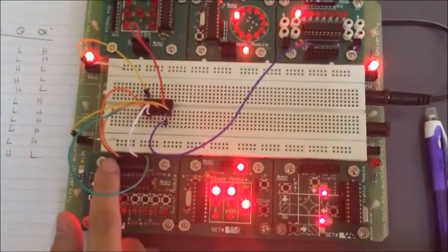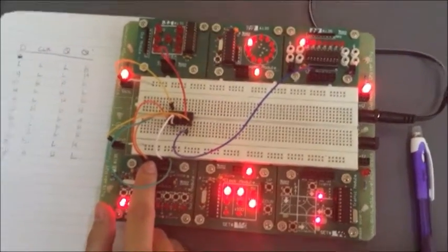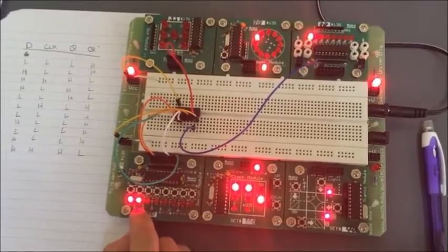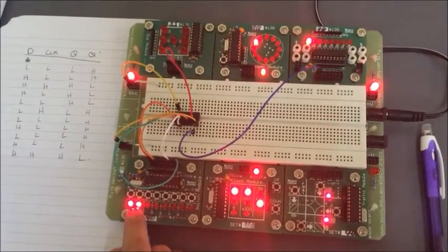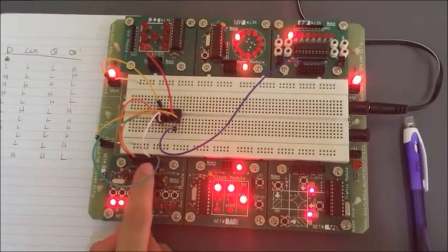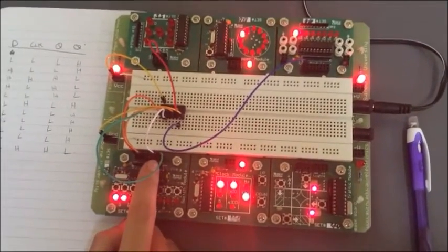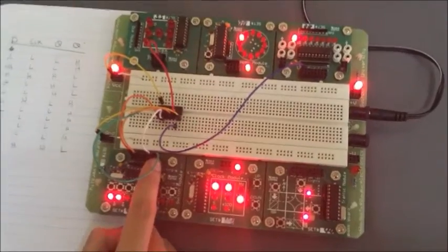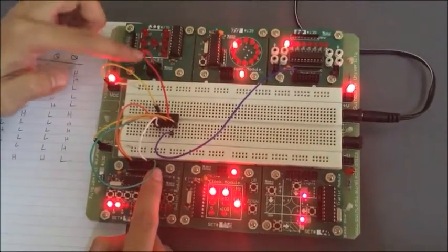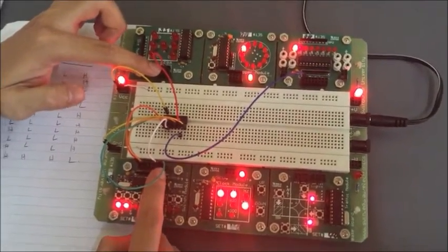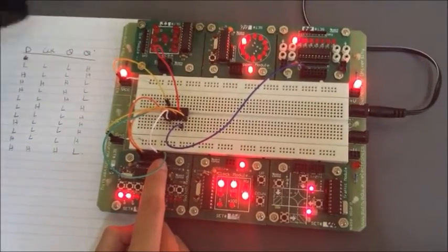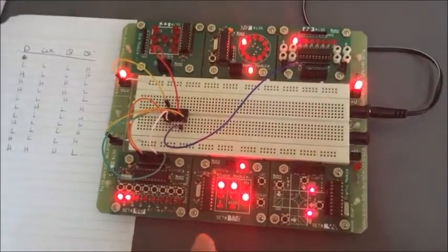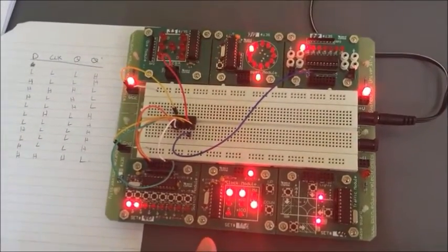Pin 1 is the reset button and pin 4 is the set input. Keeping in mind that both are active low, we would like to keep both of these lights on. Pin 2 is connected as the data input, and pin 3 as the clock input. Q is connected to the pin 5 output, and Q prime, the opposite of Q, we will be connecting to pin 6 right here. Now, let me demonstrate to you.